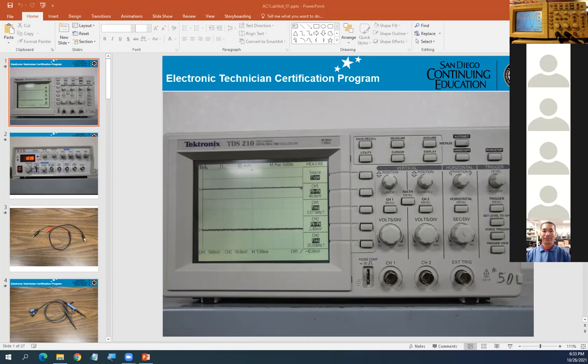If they want to measure point A only, you connect to point A, but the scope ground must be connected to ground. Remember, the scope ground must be connected to ground all the time. The scope probe only measures a single point, not two points. When you measure the voltage across the resistor from A to B, it is not only a single A and only a single B,